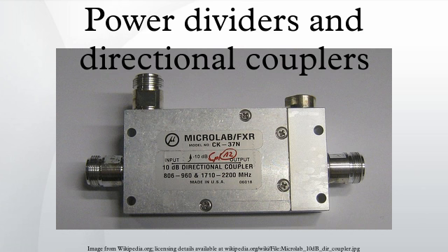The hybrid ring is not symmetric on its ports. Choosing a different port as the input does not necessarily produce the same results. With port 1 or port 3 as the input, the hybrid ring is a 0° hybrid. However, using port 2 or port 4 as the input results in a 180° hybrid. This fact leads to another useful application of the hybrid ring. It can be used to produce sum and difference signals from 2 input signals, as shown in Figure 12. With inputs to ports 2 and 3, the sum signal appears at port 1 and the difference signal appears at port 4.